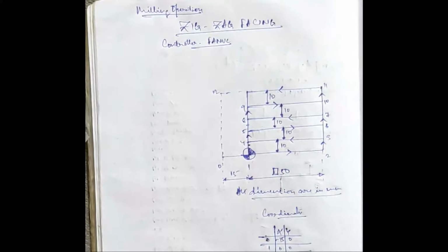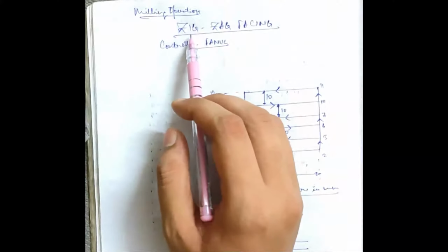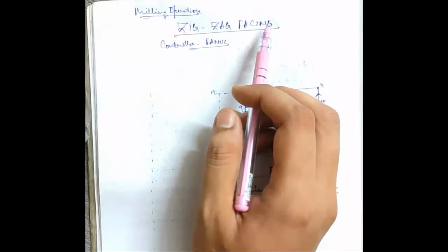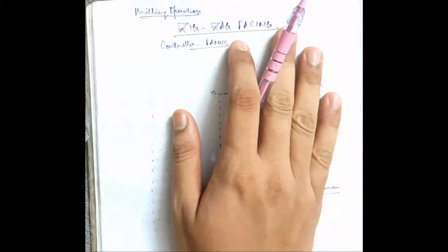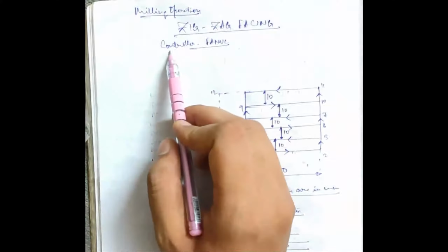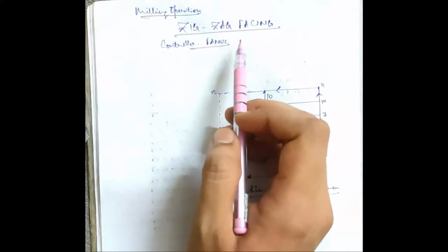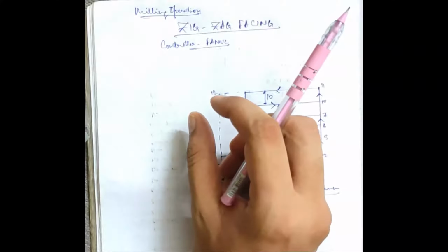Hello friends, today we are going to learn about the milling operation. Okay, so first is your zigzag facing. Why is facing done? Facing is done to get a uniform surface. Okay, that's why facing is done. The controller is, as usual, the Fanuc. Facing is also done to get the exact thickness or exact height of the workpiece.